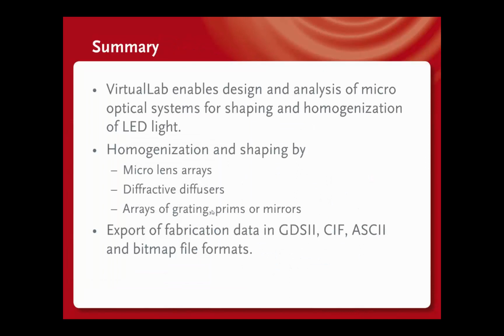So I would like to summarize this webinar. VirtualLab enables design and analysis of micro-optical components for shaping and homogenization of LED light, and I showed you especially homogenization and shaping of LED light by microlens arrays, diffractive diffusers, and arrays of grating, prism, and mirror cells.